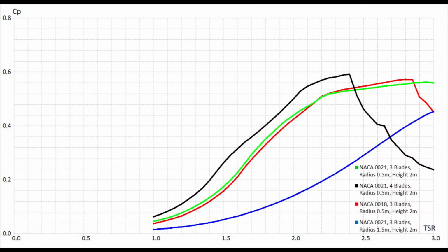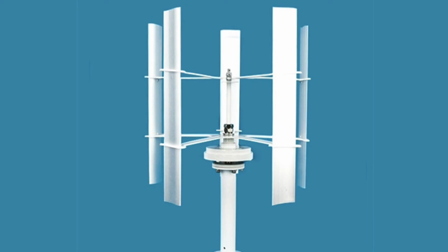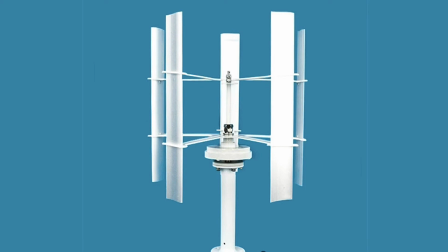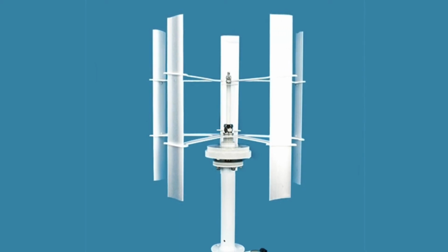This graph was obtained using the QBlade software. In the x-axis we have TSR, which is the tip speed ratio. It is a ratio between the tangential speed of the foil tip and the speed of the wind. The y-axis contains the CP, which is the power coefficient. We must maximize this value for our range in order to find the best design that will give us the best power production. The data shows us that this design would give us the best power compared to other designs for the wind speed here in the UAE.